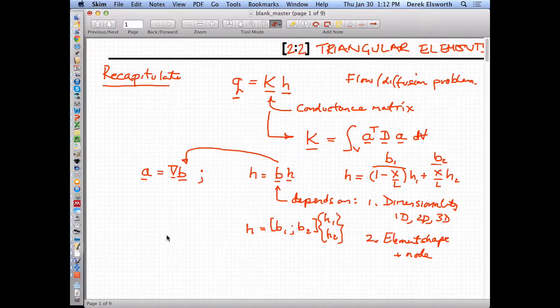The other matrix that we have was our constitutive matrix. What is that? That is equal to flow velocity, which is equal to the gradients of head, where these are the nodal values of heads. Is that right? That's not right, is it? Yeah, so it would be this. And this is just Darcy's law. So in our particular case, D was just equal to hydraulic conductivity, a 1-by-1 matrix with value 1, nothing more than that.